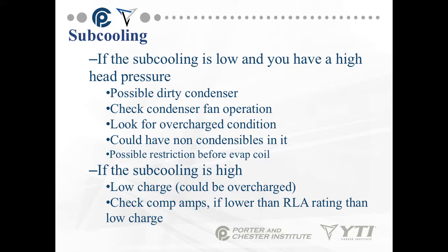If the subcooling is high, look for a low charge. Sometimes it could be overcharged a little, but most often it's a low charge. Check the compressor amps. If lower than the RLA rating, then you have a low charge.